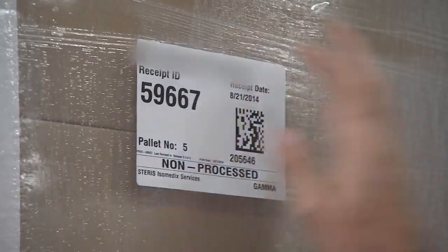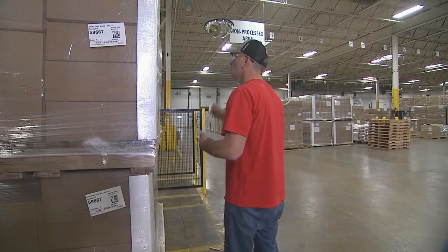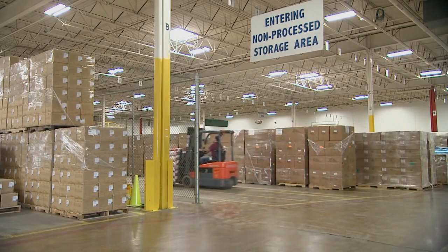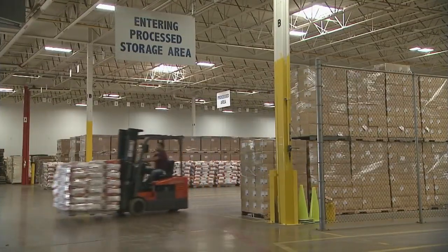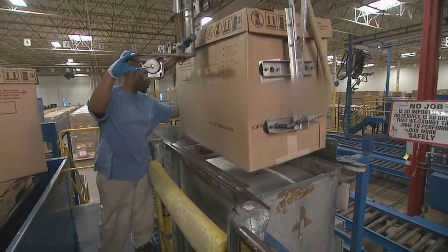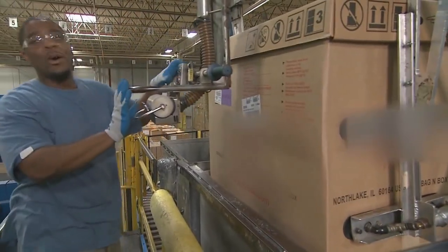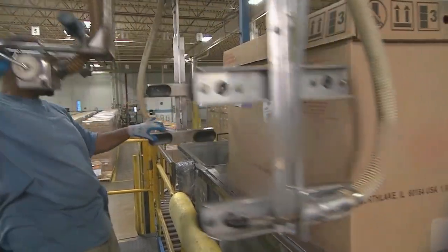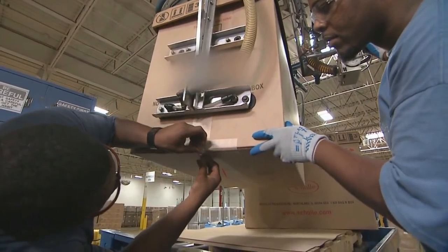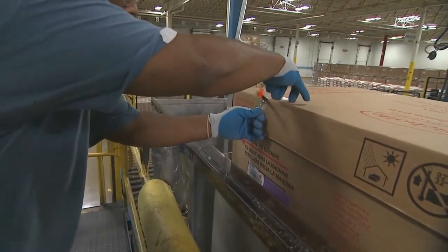The process begins when unopened boxes or other containers are retrieved from the secure, non-processed side of the warehouse. This area typically includes a fence or physical barrier between the non-processed products and those that have completed the irradiation process. Products are carefully loaded onto a material handling system. They are usually put inside aluminum carriers or totes. Each load is designed to ensure the specified dose is delivered. Then, process monitoring devices called dosimeters are placed at previously determined points on the product to measure the delivered irradiation dose.